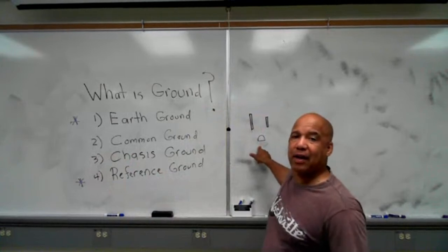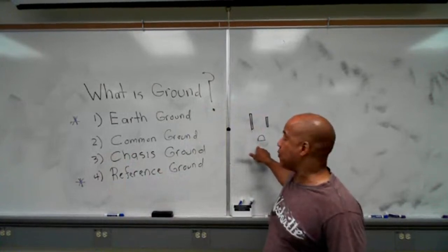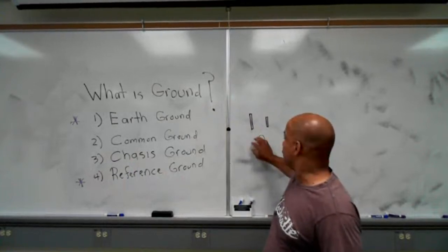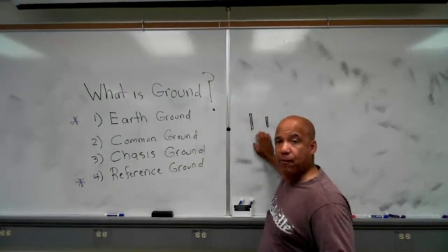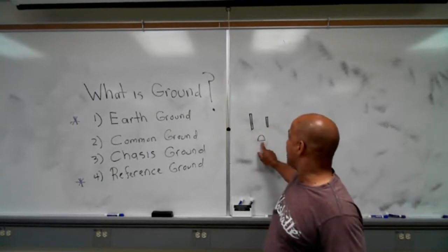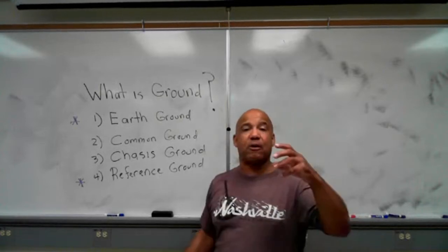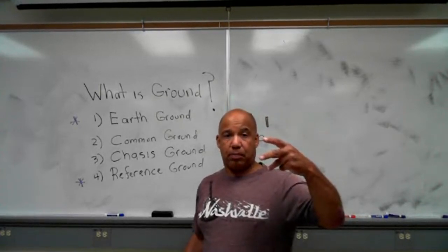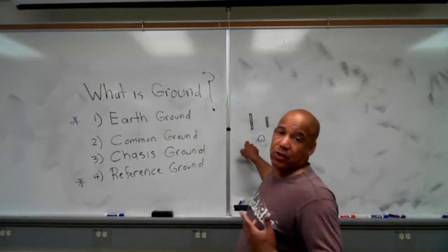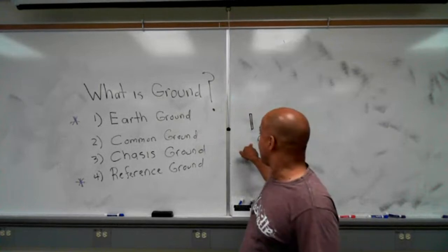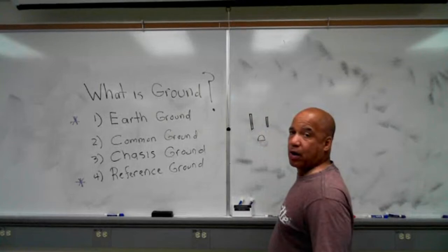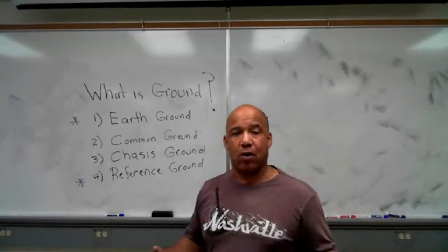And if you live in an older house, I do real estate investing. I have a couple properties that I rent out. And my older properties don't have that ground prong. It's just a two-blade plug, and most devices you buy now are three blades. They have that ground prong, so I have to go through, and either you buy an adapter, which will turn the three-prong plug into a two-prong plug so I can plug it into here, or you replace those receptacles with three-prong, which is usually what I do, just for convenience of the tenant. But as I said, if you can shrink down and go into this little hole here and trace the wire where it goes, you will see it physically ties to earth.